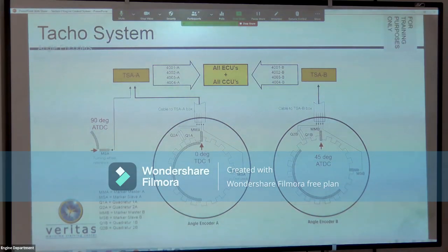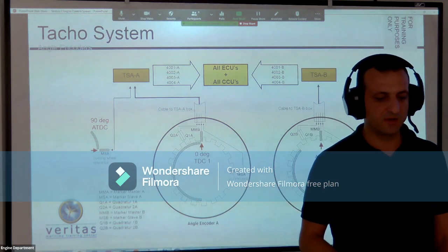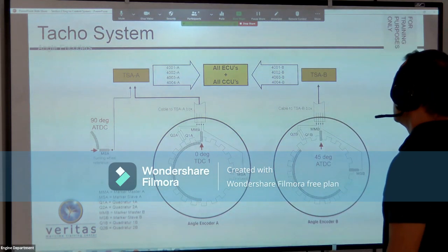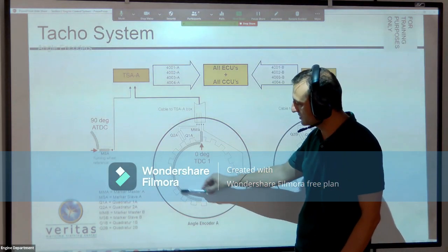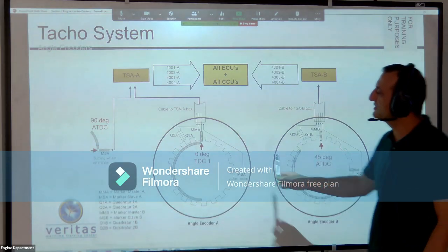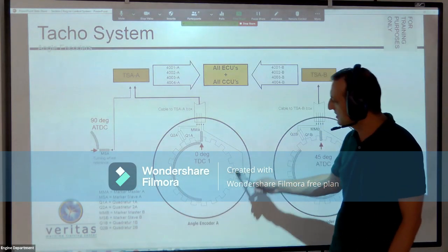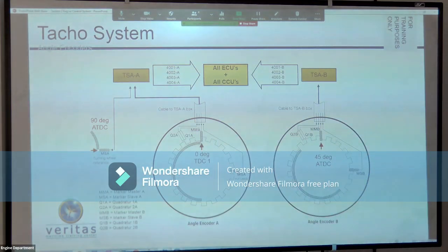There are different adjustments toward the initial position of the crankshaft. On the hollow shaft, on the rotational part of the encoder, you will find a semicircular ring. Both encoders are similar: a semicircular ring and the 360 teeth ring. They are fitted on the hollow shafts, so they turn with the engine revolution.